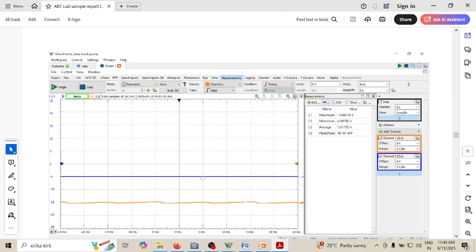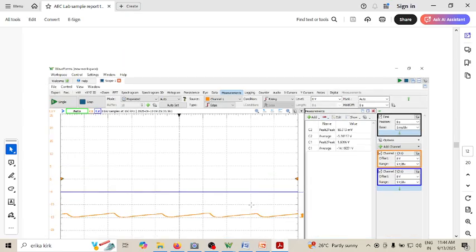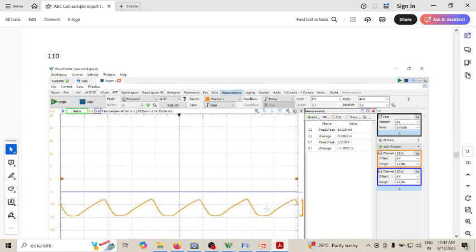And you can see this is a regulated voltage. Can you see this is at minus 5 volt? You want to get a minus 5 volt regulation, and you are exactly getting minus 5 volt. And you can see there is a very small ripple of 48 millivolt, whereas this has a huge ripple of around 600 millivolt. Then comes, okay, now this is your load regulation. I will show you the line regulation also.